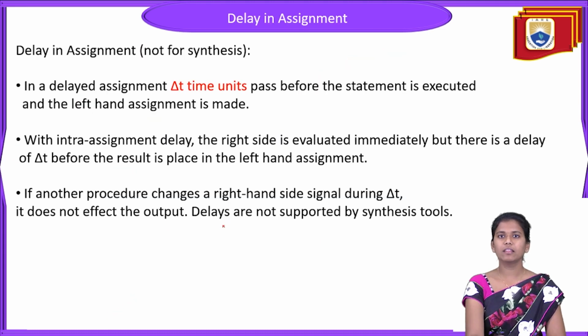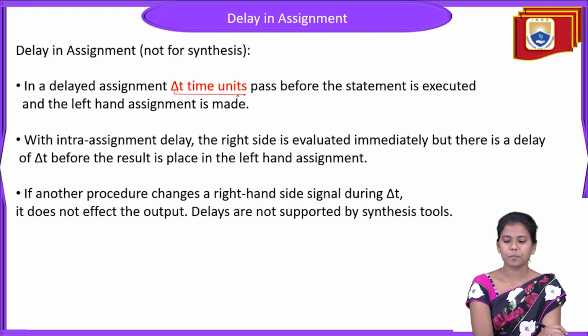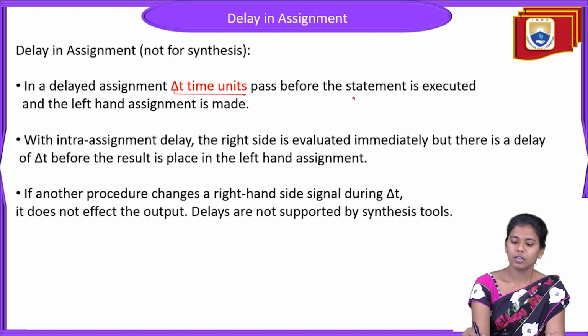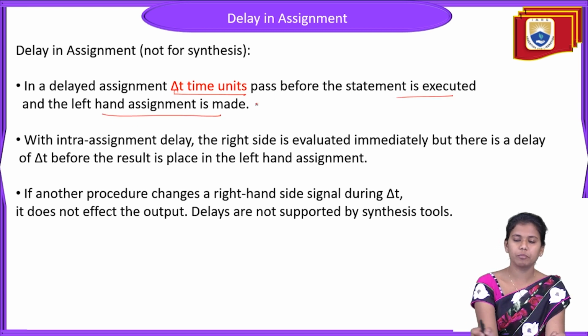Now, how the delays in the assignments are produced, or how they can be calculated, we will see. Delays in the assignments are not for synthesis. Here in the delay assignment, delta t time units pass before the statement is executed and the left hand assignment is made.